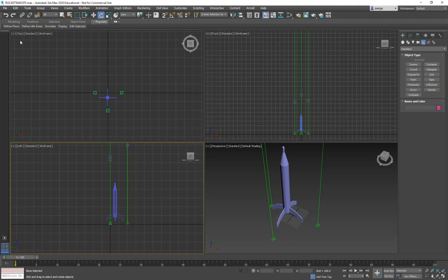But so far, I need you to accomplish what we did in this session. Add the MassFX toolbar and make sure that you add the properties of mass to the rocket, and 3 measuring tapes indicating 3 different elevations. Next class, I will assign initial velocities and then discuss this issue. There's a very technical issue about the initial velocities that I want to discuss with you next class.